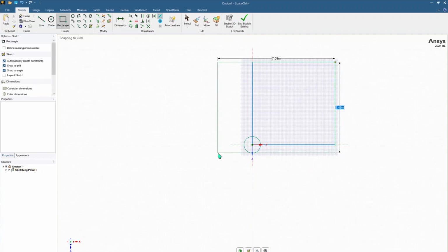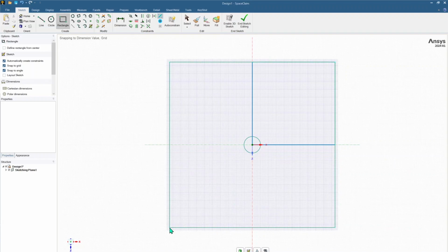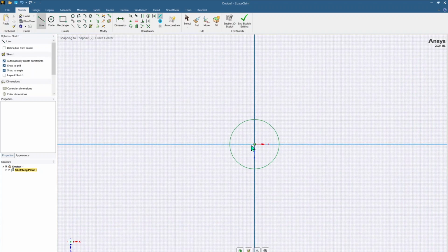The important thing here is, if you want to create a structured mesh in a surface, in a subsurface, you need each surface to have 8 nodes. This is the reason why I divide my surface like this, so that each subsurface has 8 nodes.